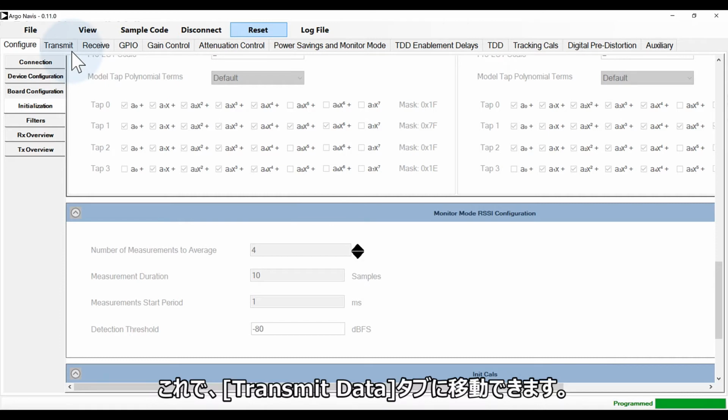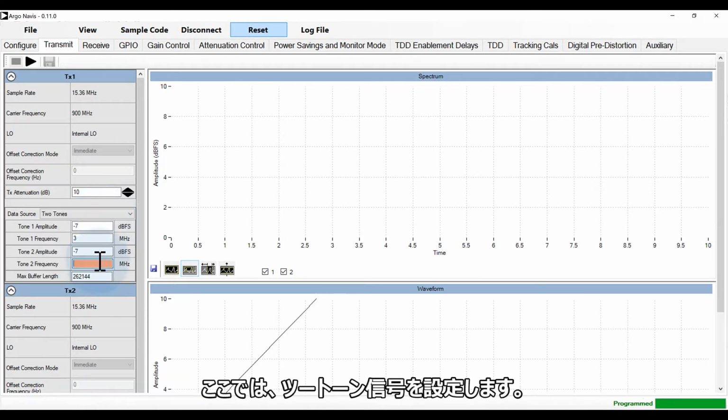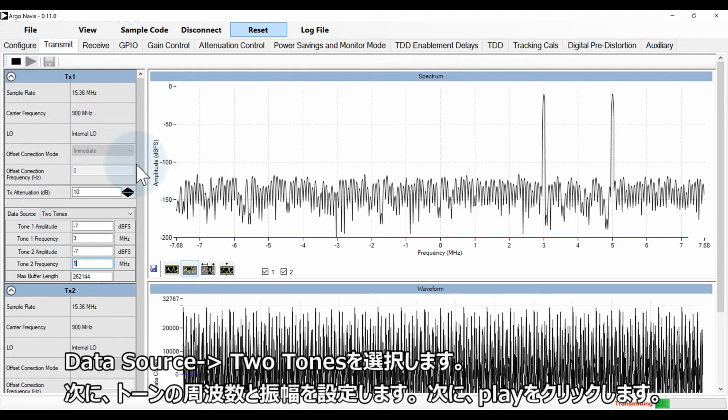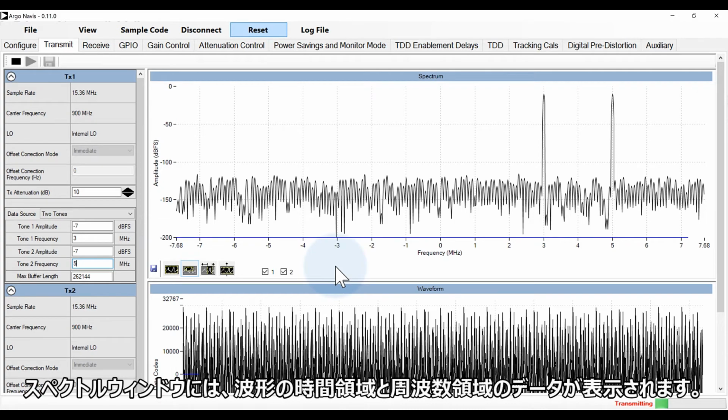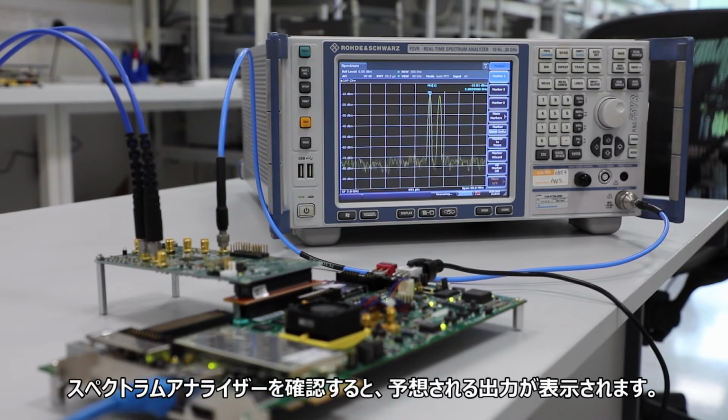Now we can move to the Transmit Data tab. This tab can be used to generate CW tones and load data vectors. Here I'll set up a two-tone signal. I select Data Source, two tones, and then configure the tone frequency and amplitude. Then I click Play. The spectrum window shows time and frequency domain data for the waveform. Checking the spectrum analyzer, we can see the expected output.